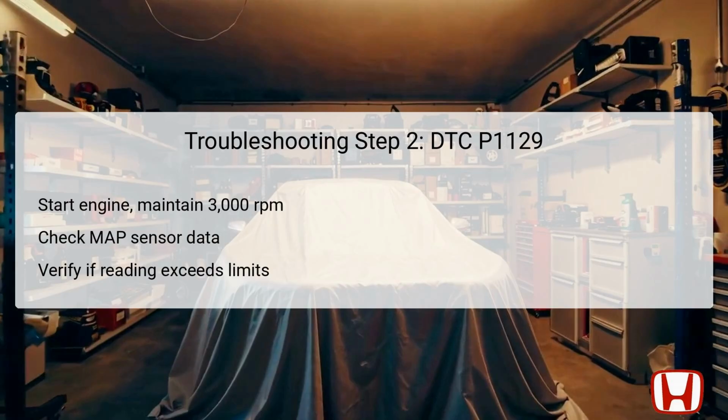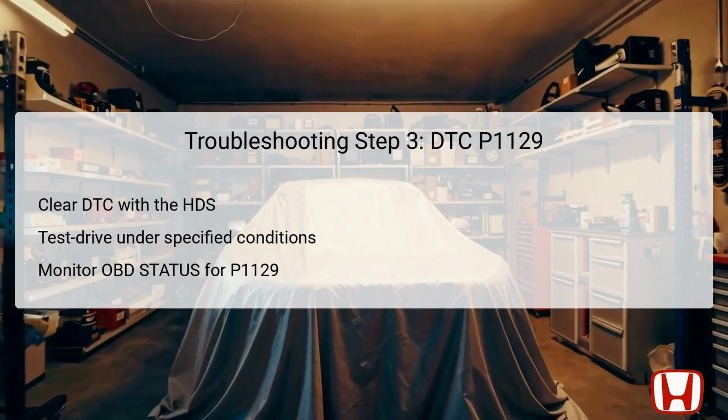If the HDS returns a yes response, it indicates that the MAP sensor is indeed faulty and needs replacement before verification steps can occur. In the third step, clear the DTC using the HDS, allowing the onboard computer to reset and eliminate any stored error codes.